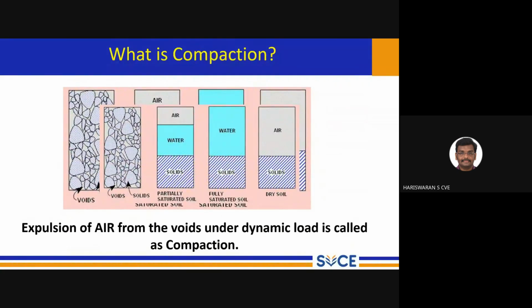This has happened because the underlying soil got compacted because of repeated load. So to replicate that, we well define and plan how much energy is going to be transferred. We compact the soil during the construction itself. So that is what the subgrade is. To compact it, we are supposed to remove a maximum amount of air from the soil. But we are not at all able to remove 100% of the air from the voids. There will be some remaining.